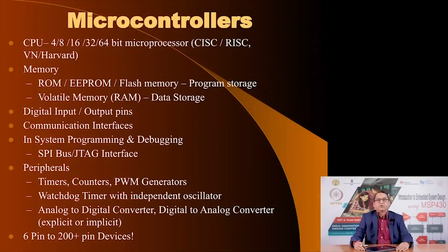To be able to download the program from your development platform into the memory, there would be pins which support these days what is called in-system programming, and through some pins you may also be able to debug the program after you have downloaded it into the memory of the microcontroller in case your application isn't working in the way that you expect it to.